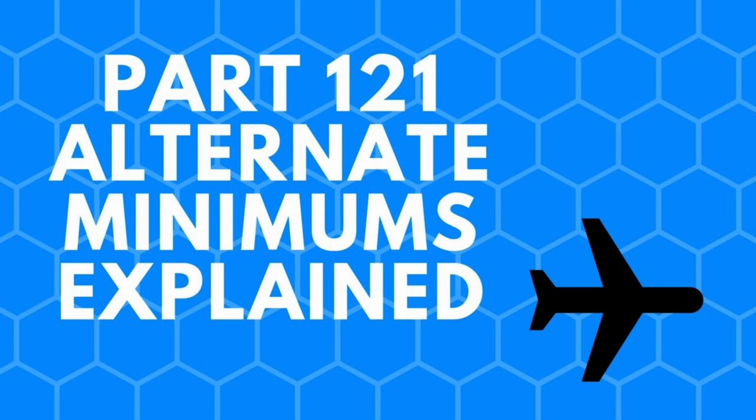The alternate must be within 2 hours flying time for an aircraft with 3 or more engines with an engine out in normal cruise and still air. For 2-engine aircraft, the alternate must be within 1 hour. The airport of intended landing may be used in lieu of an alternate provided that it meets all the requirements.